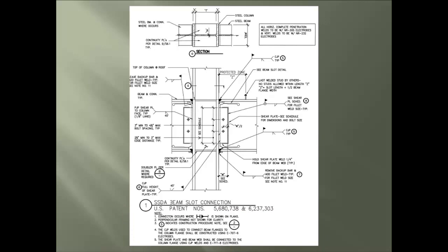To go over a few tools found on this detail that will help finding the answers also are the weld symbol. We will cover these in more depth later in this seminar. Next is a specific detail view call out, which is the upper part of the circle states to look at number 9 detail, and the dashed line in the bottom part of the circle means you stay on the same page as it's found. And lastly is the symbol for full penetration weld connections, which is the same as we reviewed on the plan view earlier in this segment.